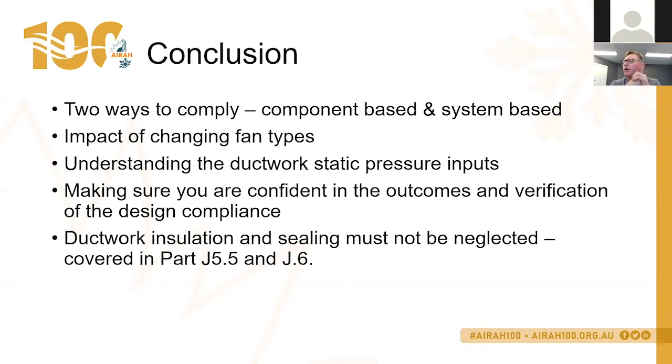Can we go with higher friction rate for kitchen exhaust duct? Well, when you look at the calculator, you'll actually see that kitchen exhaust systems do not have to comply. They come up as not applicable. So I'd say the answer there is yes. Kitchen exhaust systems are not assessed.